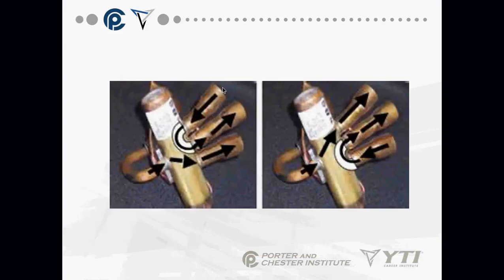So when we're in one mode of operation, we're coming this way, and we have a U shape here. When we're in another mode of operation, the slide has slid over this way, causing my U there, and my bypass is here. So it all depends on where that little U is that's mounted inside that reversing valve.